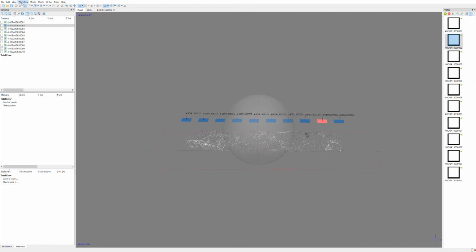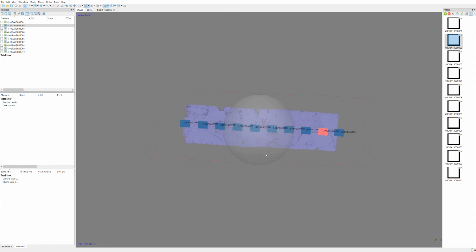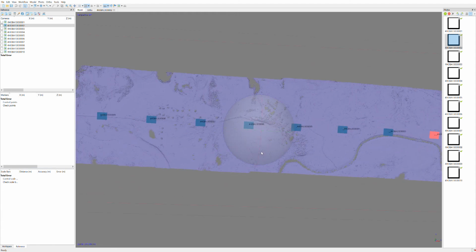So now we can go to build our dense cloud, and again you'll want to save here. There's a step in the dense cloud that you might find out the hard way, that you need to change a setting or else your computer might crash. It automatically put depth filtering as mild. I usually run as aggressive, so I'm going to keep that there. Quality high. I'm not going to calculate point colors. It takes a little more time and it's black and white, so I don't really care. And just press OK. We have created our dense cloud,